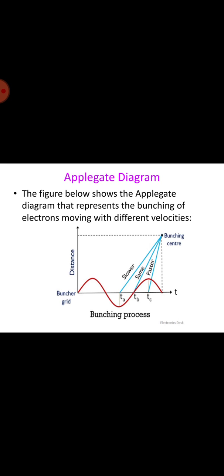Any electron arriving after the second limit was not accelerated sufficiently to catch up with any electron passing through gap A just before the first limit. So bunches arrive at the catcher grid once per cycle and deliver their energy to the cavity. The catcher cavity is excited into oscillations at its resonant frequency, and a large sinusoidal output can be obtained because of the flywheel effect of the output resonator.